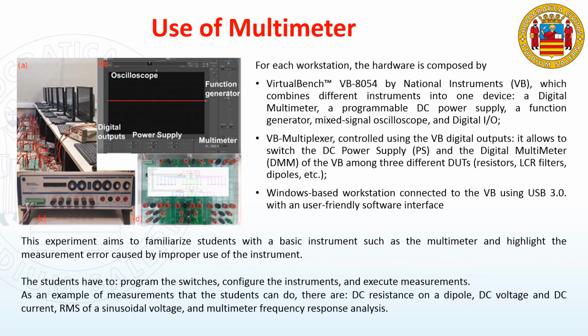One of the first experiences of this course is the use of the multimeter. For this kind of experience, each workstation is provided with a virtual bench, a hardware made by National Instruments, including different devices: a digital multimeter, a programmable DC power supply, a function generator, a mixed signal oscilloscope, and several digital I/O. In addition to the virtual bench, there is a virtual bench multiplexer controlled by the virtual bench digital I/O in order to switch the DC power supply and digital multimeters of the virtual bench among 3